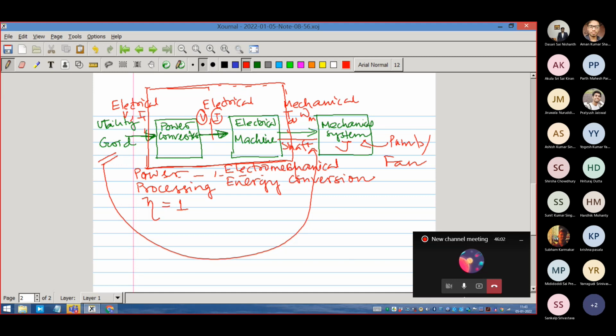I will give you an easy example. The torque, I said, is flux times current, right? So when the machine is demanding a torque, I just have to increase the current without increasing flux, because increasing flux will make it saturated. So I have to have a control system, or give such a voltage at such a frequency, that the flux is unchanged but the current is changed.